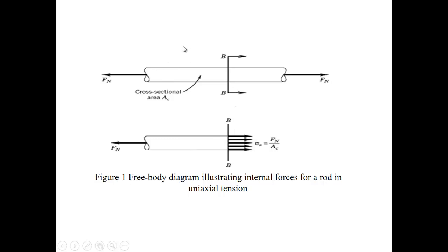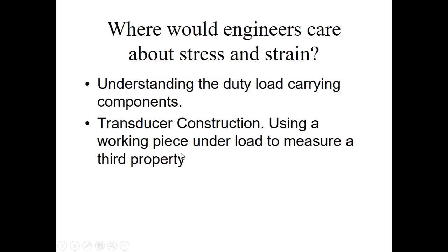So this is how we illustrate the calculation for a stress. When you have some structure and you give a tension direction force acting on the structure, to find the stress, the stress is equal to the force divided by the cross-sectional area of the structure. So you will get directly the internal stress acting on the structure or the beam lah, or the rod.